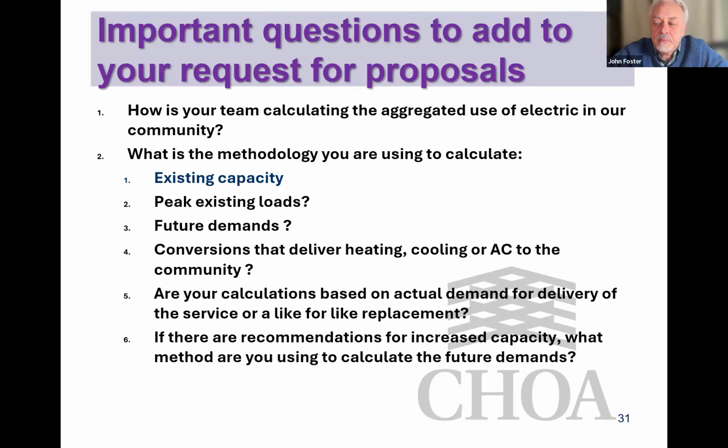And then you can pick the highest one, which is usually January or February, and then multiply it by a factor. And that's where it gets a little difficult to answer which kind of factor to convert it to the actual peak, because that is just an hour. And then looking at the peak loads, looking at the equipment, correlating it with that. Is there a peak in the summer for air conditioning more prevalent in the Okanagan?